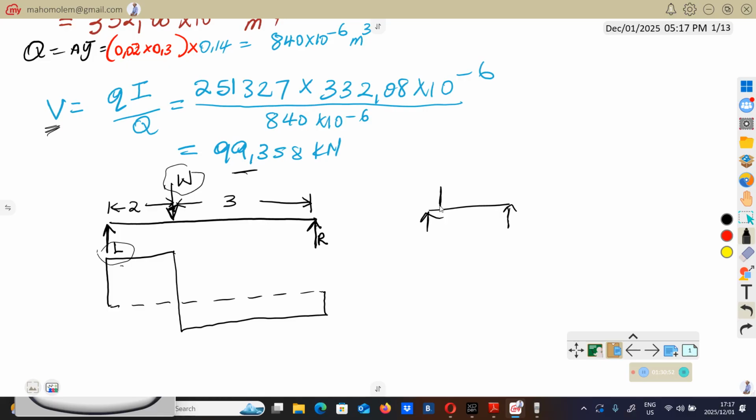If the load is placed next to this side, let's say we have 10 kN or 10 Newton, most of the load will be supported by the side next to the load applied. So the load applied is next to the left reaction, so this left reaction is going to carry more. Maybe you'll find that it carries 7 Newton, and this one, which is far from the load, is going to carry less, 3 Newton.